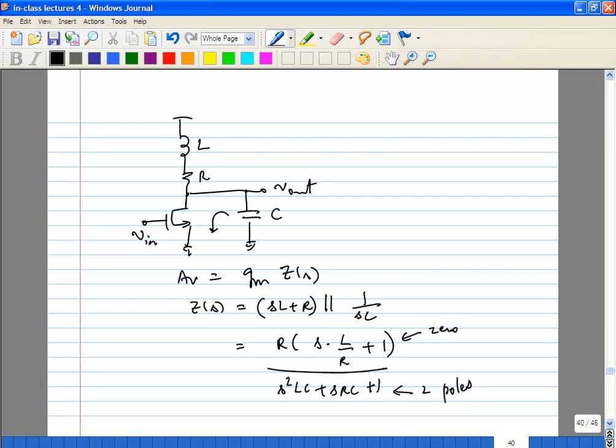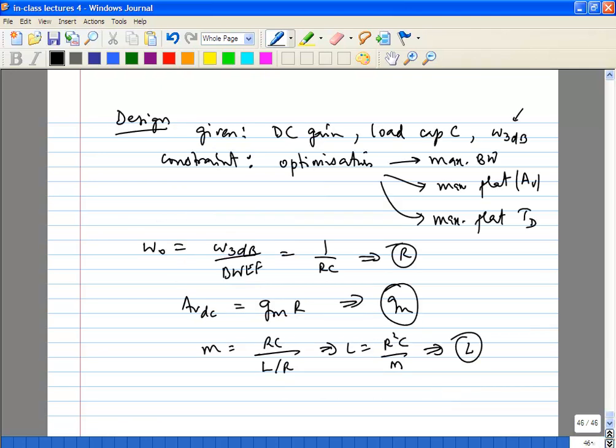Then quite common is having multi-layer inductors, except not in shunt but in series. So you'll wind the inductor on one layer, you'll go down, wind it in the same direction so that it adds magnetically, and keep doing it. The only thing you have to care about is self resonance.